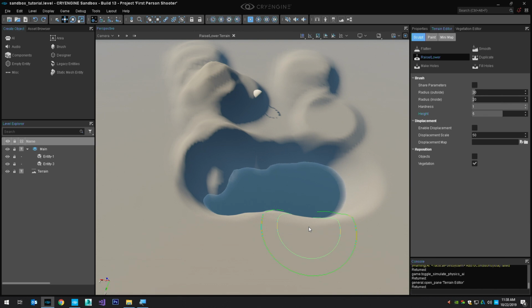How low do I have to go to get the water? So here are some important numbers. The default position of the terrain in CryEngine is 32 meters, not 0, 32 meters. You can set it to anything. If you want to do 0, do 0. That makes sense to me. It just happens to be at 32 meters.